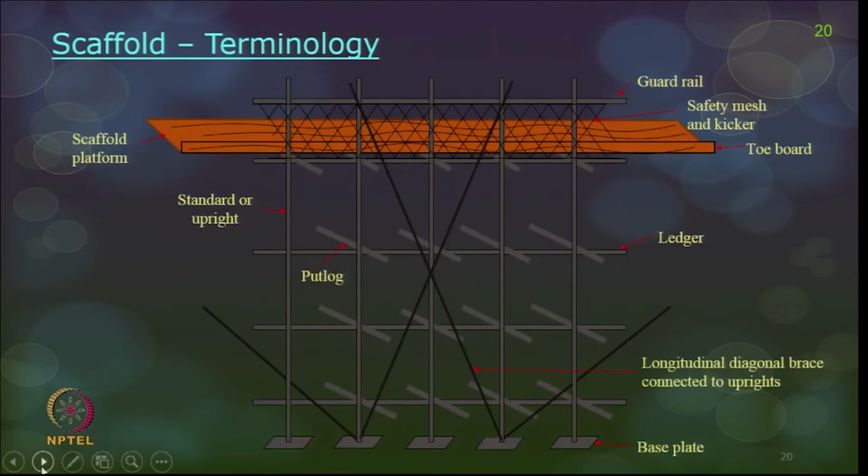If you see some pictures of the scaffold, these are the pictures and all the parts are labeled here. And if the scaffold platform is not stable, then you can also have a base plate, so that the scaffolds are firmly put in place.